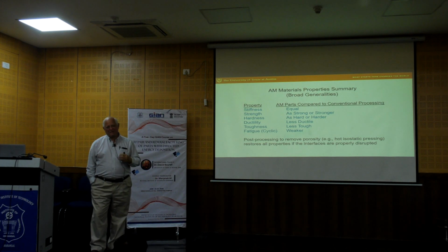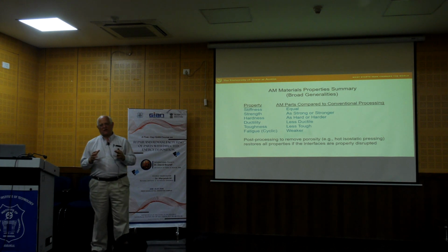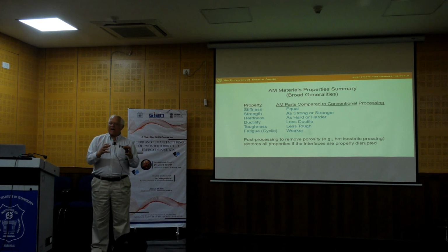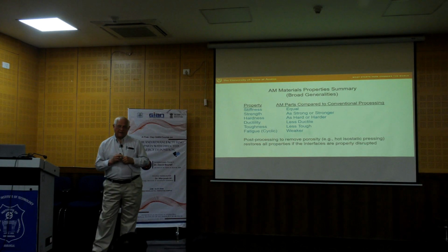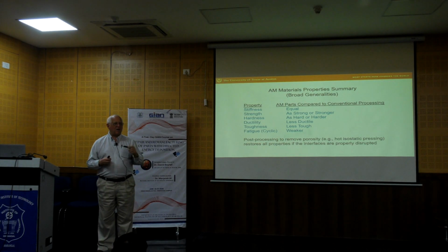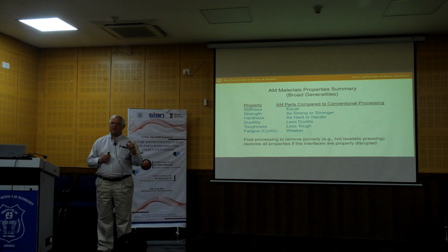And the reason that's generally given is that with additive manufacturing, the cooling rate is fairly high compared to, say, a forging or a casting, and what it results in is a finer structure, and we get basically a Hall-Petch-style strengthening effect. I always say that, and I always follow up by saying that people that actually do the calculations based on the Hall-Petch equation find that the strengthening is greater than what Hall-Petch would predict.